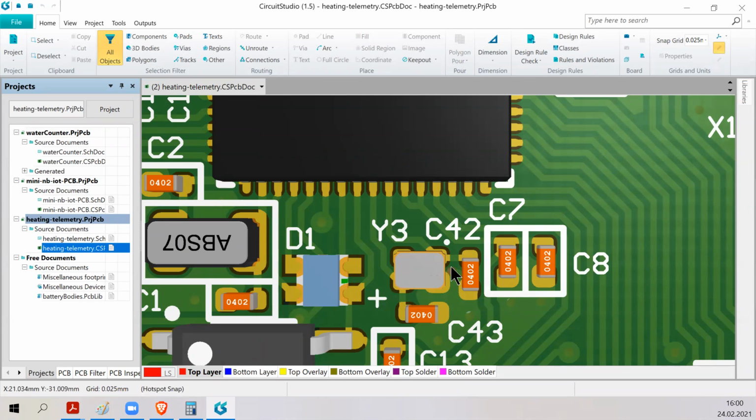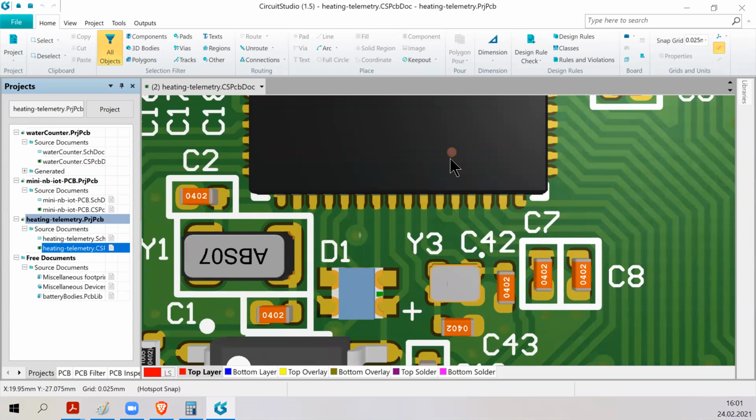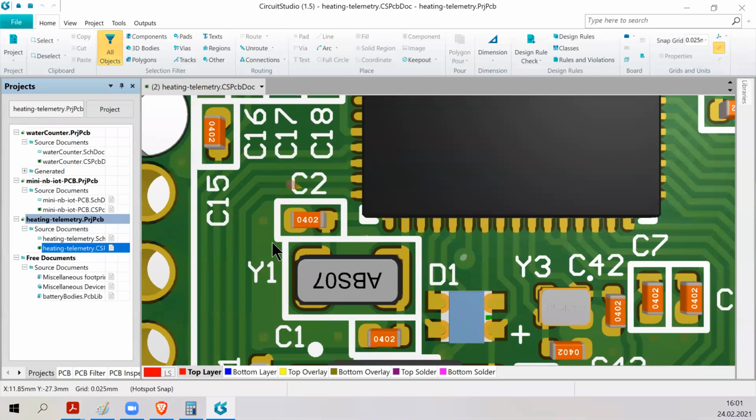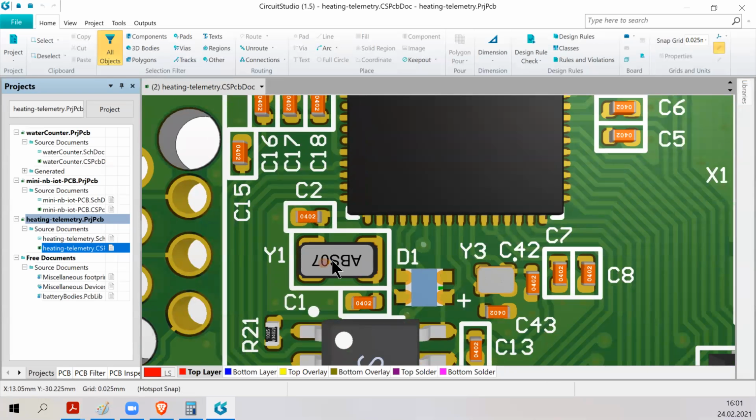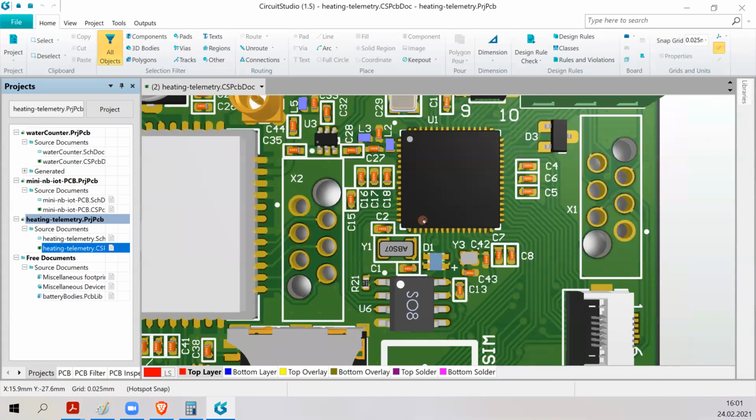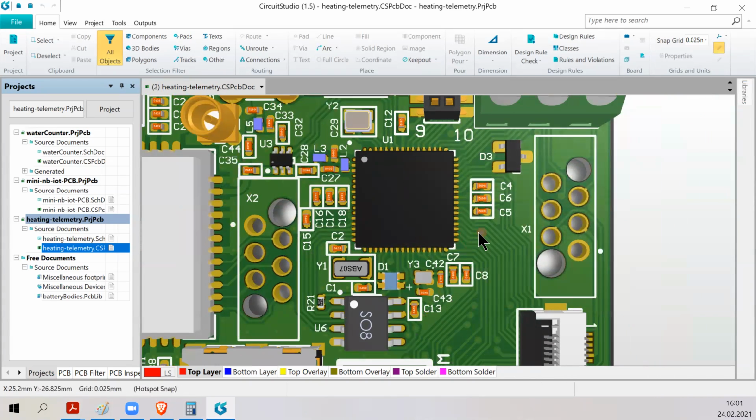Let's just drop it. Let's not use this thing. And let's run high frequency tasks from the internal oscillator. And only the clock, the second counting or minute and hour counting clock, runs from this precise oscillator. Okay, something like this.